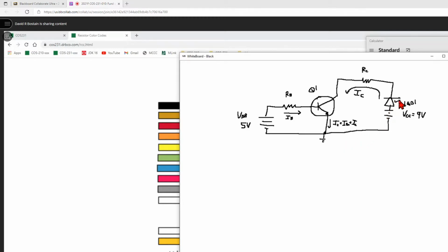Now, because we're turning the LED on, we want the transistor to be able to provide as much current as possible, meaning we want the transistor in our design to become saturated. That's an important step. We don't want it in the active region because if it is in the active region and this varies slightly, then the light will dim and get brighter. The saturated region will pick a current and make this stay at that current, or within 5%, 10%, whatever we decide our resistor value should be. Here are the values for our problem, and we'll see how to work it.